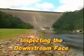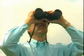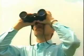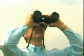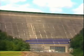Now let's turn our attention to the downstream face. Because of the difficulty in viewing the downstream face of a concrete dam up close, it should be inspected first from a distance, through binoculars. When using binoculars to view the downstream face, develop a systematic scanning pattern to ensure that you observe the entire face.